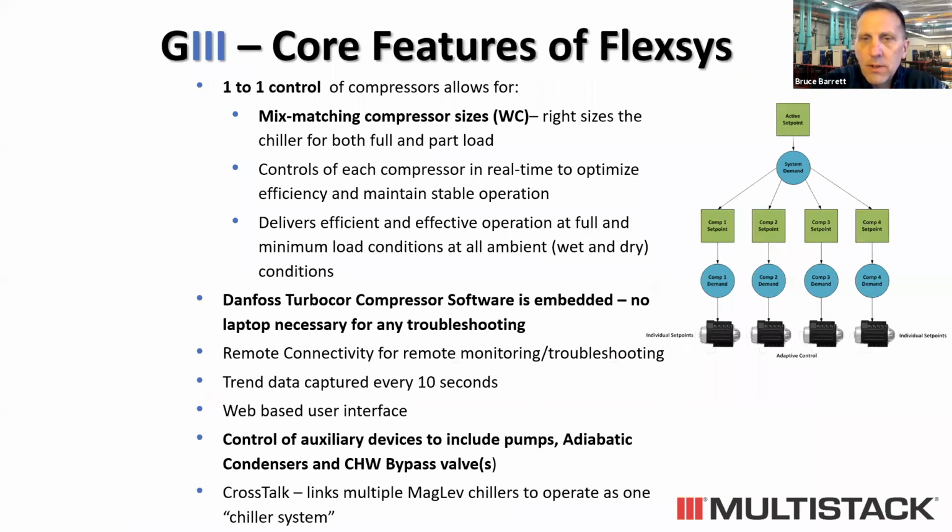What makes our compressor controls so good and different, really different? The modular environment: we had to control compressors and stage them independently. We have a system demand that can communicate directly via Modbus to each and every compressor. We can operate different compressor sizes at different speeds, keep them safer, improve our transitional efficiency as air temperatures or condenser water temperatures or load changes. We can precisely control those compressors one-to-one.